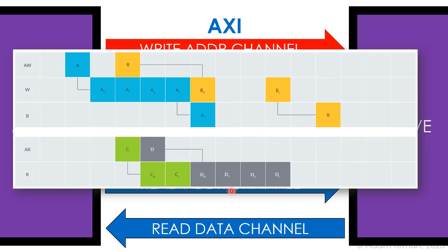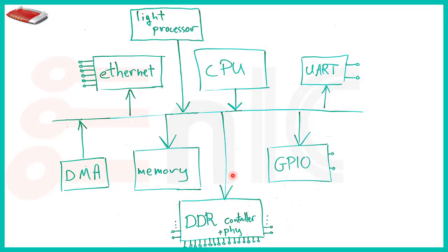And it's more like a network on a chip than just a simple bus like the APB or AHB that we saw before. So really, we kind of completed our whole design over here, and now we understand how we talk to the DDR controller using an AXI type of bus rather than AHB or APB, which we saw didn't support the actual speeds we need.